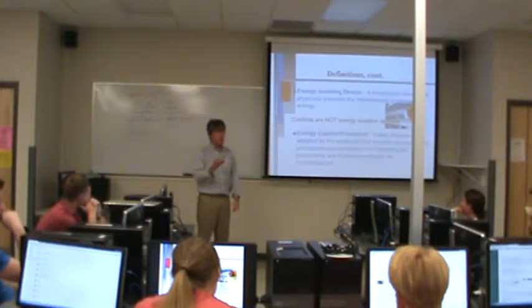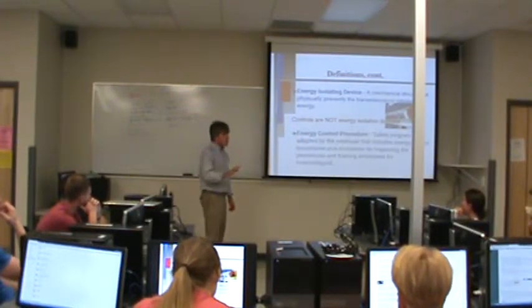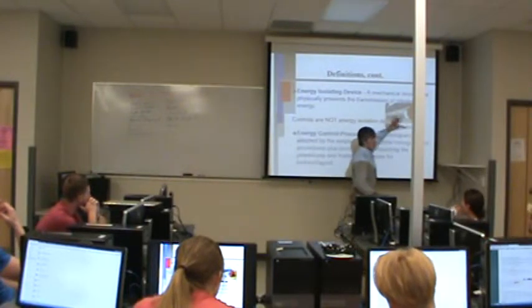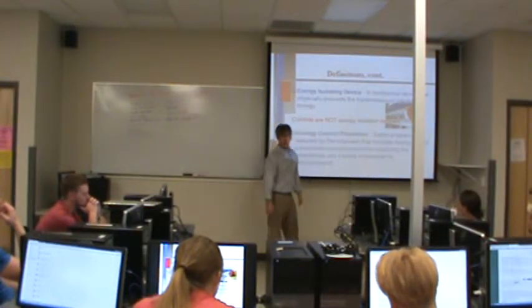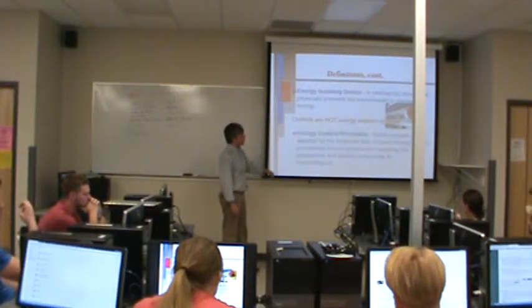Just because the machine has an E-stop, a red mushroom head E-stop, that is not an energy isolating device. You know why? Because somebody can come, turn the E-stop, it pops back out, and the machine's live again. Okay? So no controls are energy isolating devices. None of these would be considered appropriate for lockout tag. Okay? Even if they've got a way of putting a lock on it, which I don't know of any decent manufacturers that have such a thing.